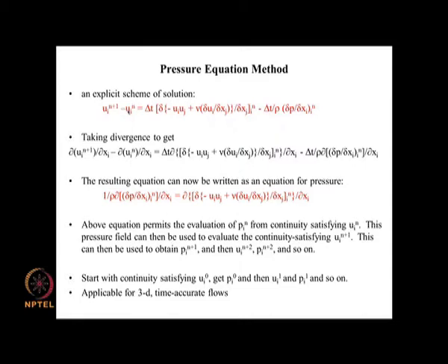First you get this, and then you get this from initial condition. Okay, initial condition, in which the initial condition is such that the velocity field satisfies the continuity equation, so that this is 0 here. If it does not become 0, then the initial condition does not satisfy the continuity equation. It is not a true velocity boundary condition. Okay, it is not a true initial solution. So we need to adjust that here. So we can construct this.